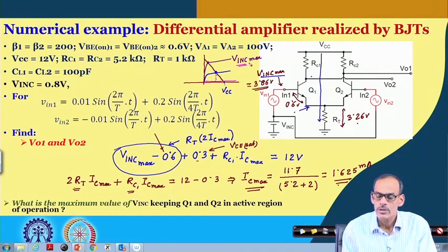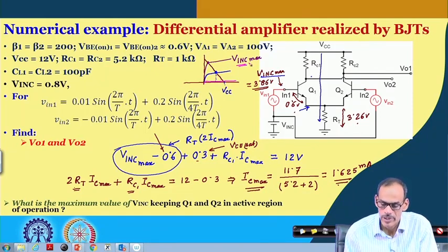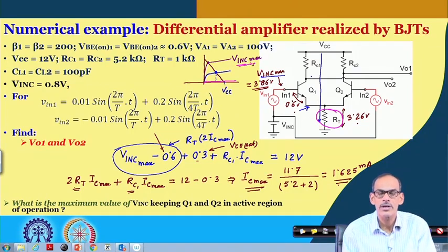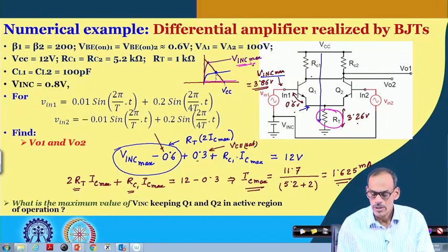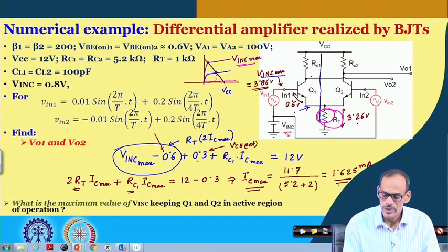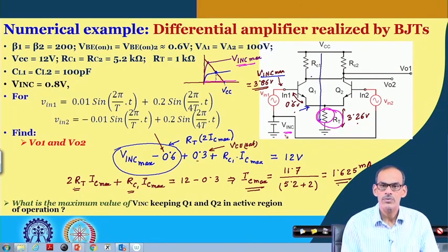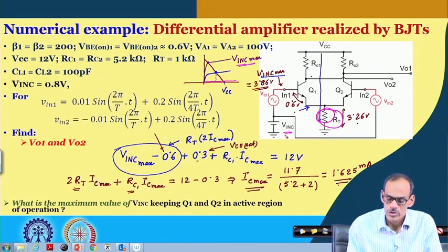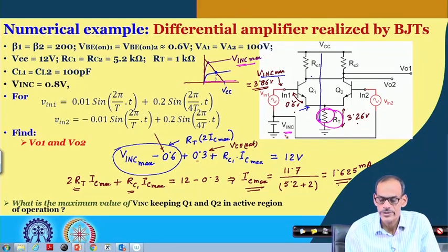So, while we will be designing this circuit, we have to keep that in mind, and since we do have passive resistor here, the operating point is very much dependent on this V in C. If we do have active device, probably then dependency of this current is not so much on V in C, but again V in C definitely will be having a suitable range. So, once we see some numerical example there, probably we can discuss the range of the V in C.